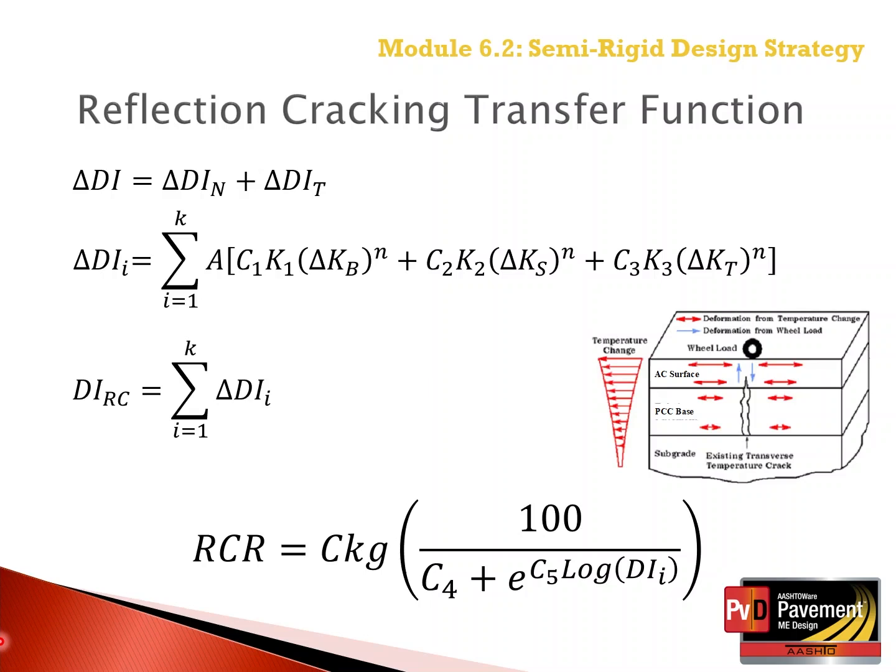Based on the length and/or area of cracks predicted for the chemically stabilized layer, so the shrinkage and fatigue cracks within the chemically stabilized layers are either entered or predicted by the software, and then our transfer function is used to predict the rate at which those reflection cracks propagate to the surface, so we can see and measure them at the surface of the asphalt layer itself.